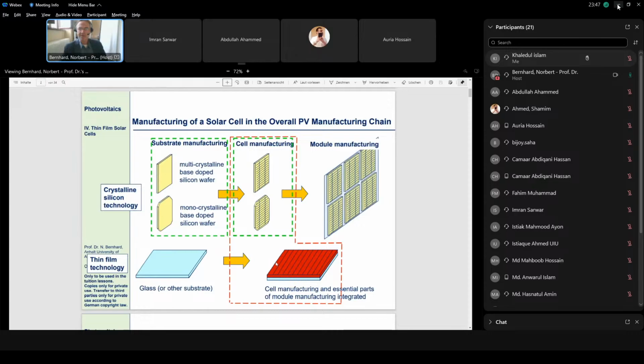And then just by controlling the temperature of these evaporation sources, the molecular beams coming out of the elements here and going towards the surfaces are controlled. And therefore, the relative composition of the films by these 4 elements is controlled. And of course, which is not really shown here, it's a vacuum technology.